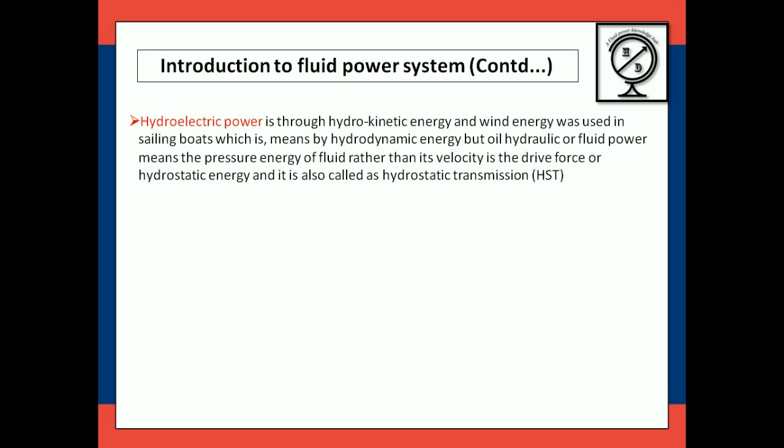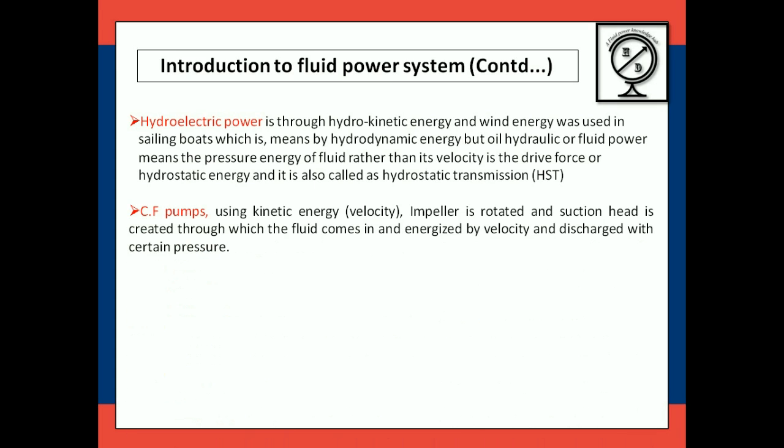which is by hydrodynamic energy. So ultimately in hydrodynamic energy, the velocity and magnitude of the fluid play a role in a controlled manner, but in oil hydraulics the pressure energy of the fluid rather than its velocity is the drive force, or hydrostatic energy, which is called hydrostatic transmission, HST.